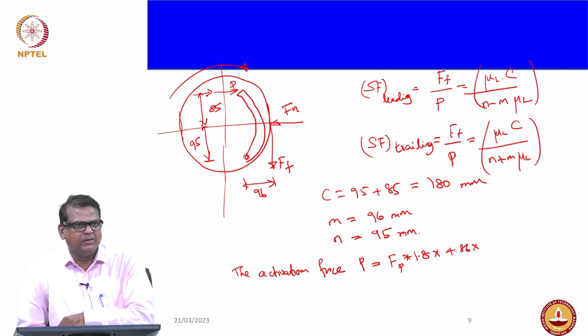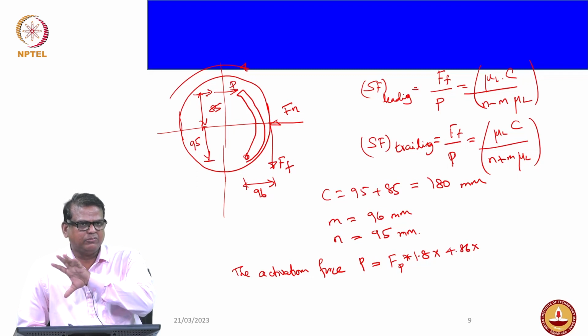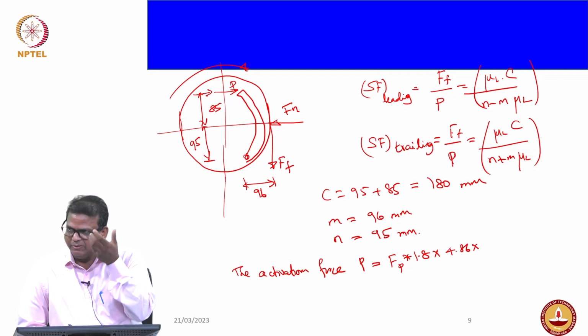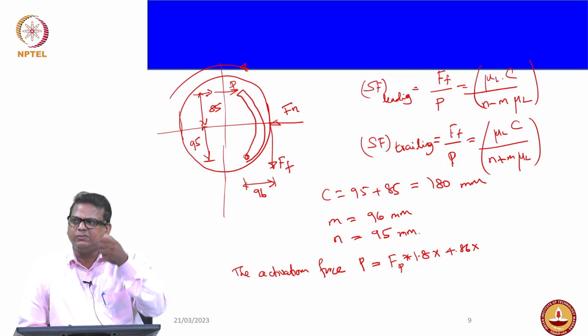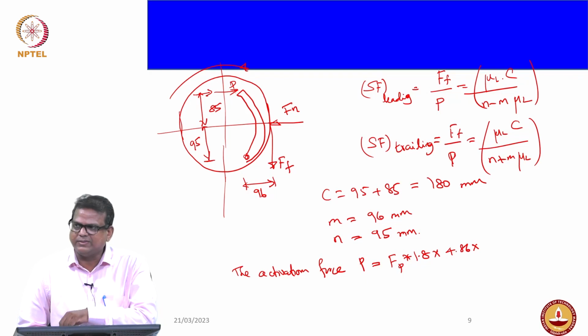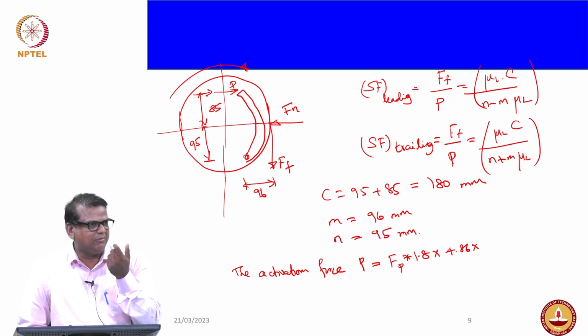Once the vacuum booster develops pressure, the pressurized brake fluid goes from the master cylinder to the wheel cylinder. The master cylinder has a diameter of 25, so the pressure will be very high.